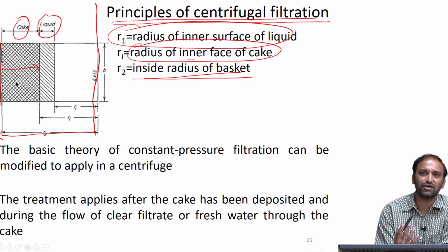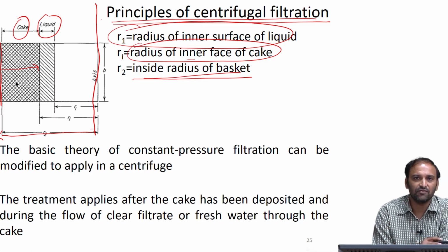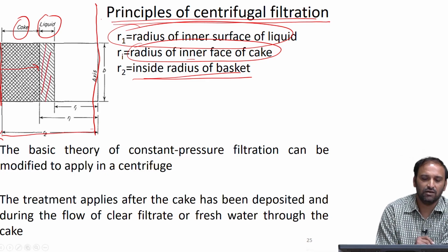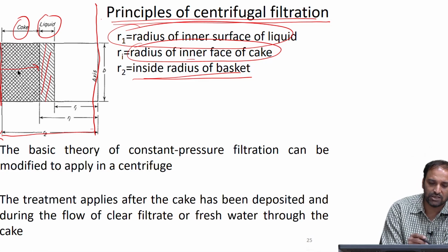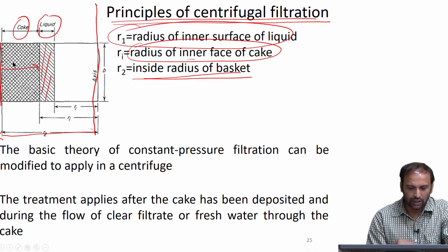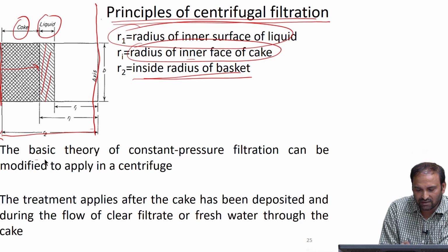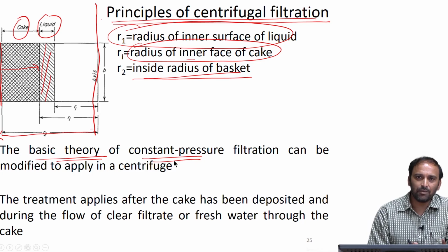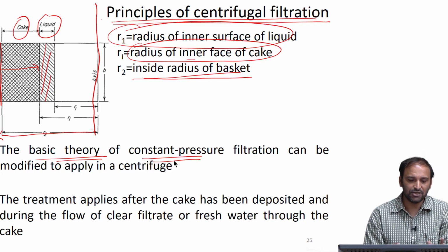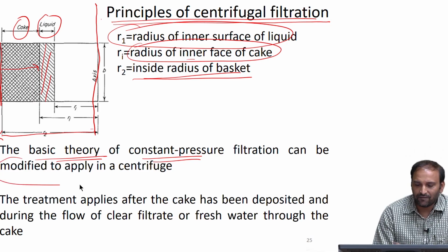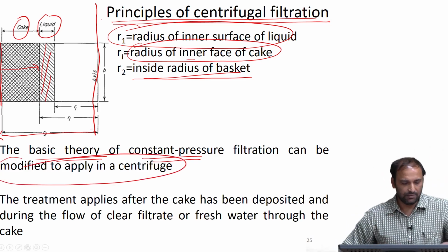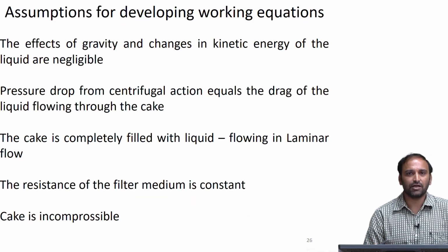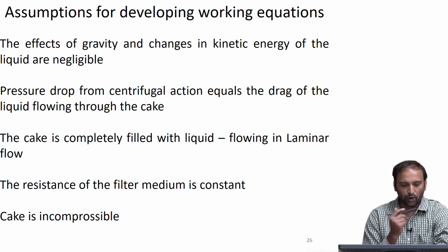And once the filtration is complete, if all the slurry is consumed, you will not have this liquid. What will be left in the end would just be the filter cake. Again in this case, whatever basic theory we have developed for constant pressure filtration, you can also apply the same kind of formalism, but you would have to modify it to suit the need of centrifugal filtration.